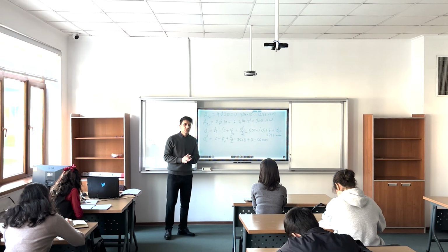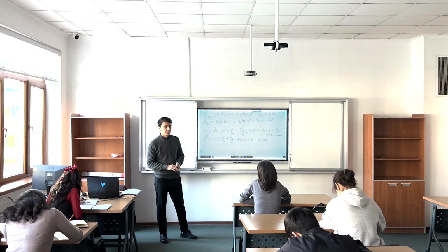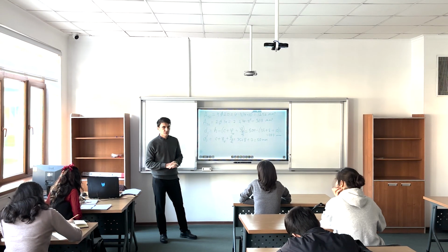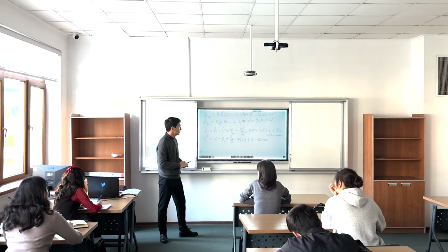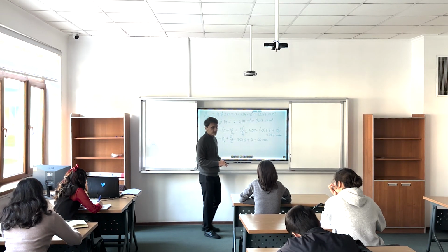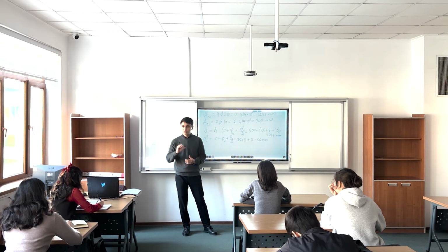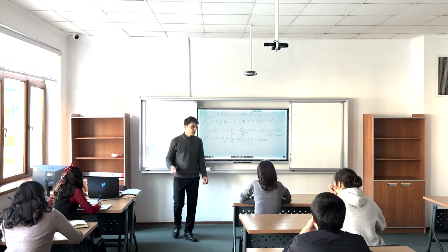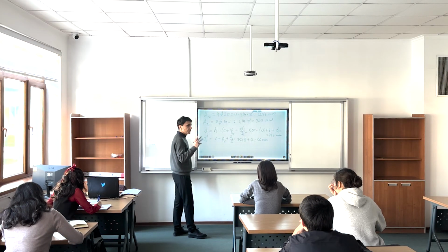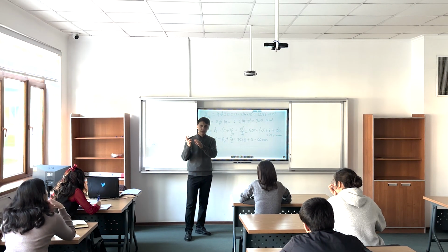Now, once we know all the characteristics of the section, our goal is to find the yielding bending moment. So yielding bending moment is found by applying the forces coming from two rebars, top and bottom rebars, and from the concrete, compressed area of the concrete. So it means we need to find three forces that are coming from the concrete, from the bottom rebar, and from the top rebar.